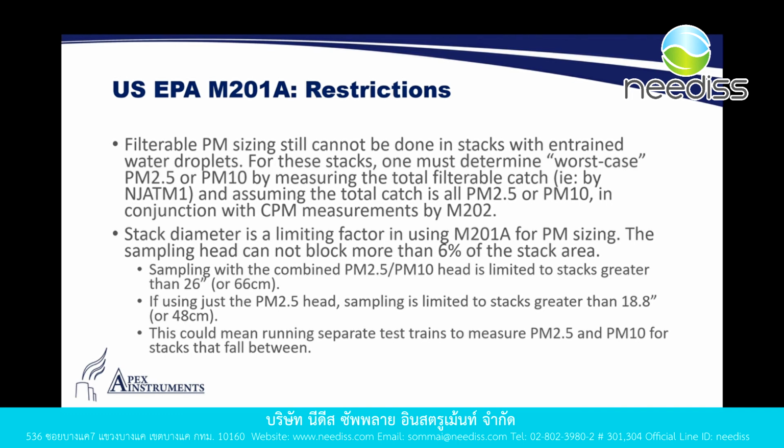What I mentioned before is that the method specifically states that because of the size of the PM cyclone head, it cannot block more than 6% of the stack area, the diameter of the stack. You cannot block the flow of more than 6% of that particular area.